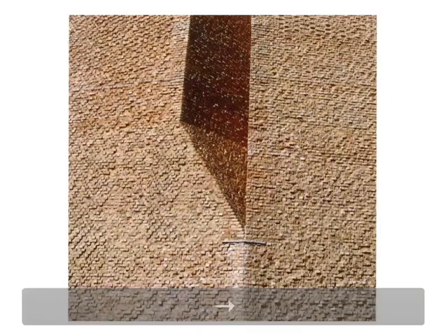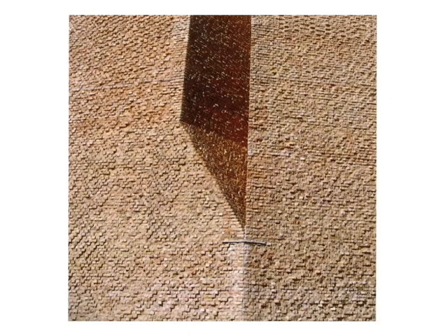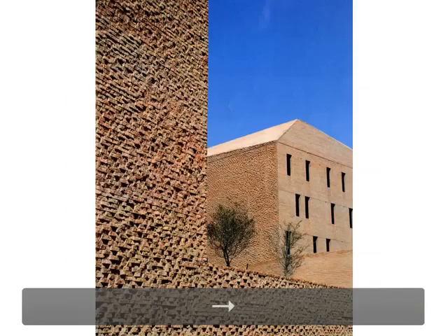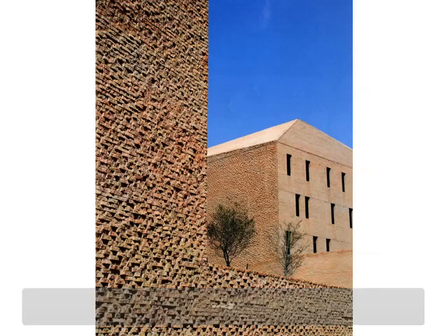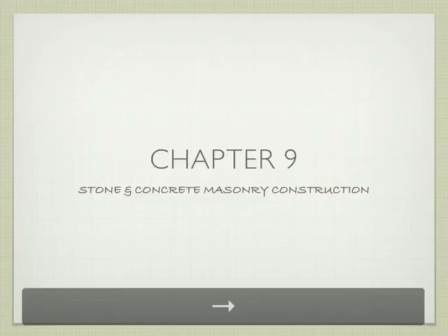So we can end up with something like this on the outside of the building, right? This would be a relatively challenging shape to try to make if it was a structural wall, right? But we have steel behind in this case that's providing the primary structure, and we can create these kinds of definitions on the surface veneer, right? Because it's only that little thin veneer, right? And so if we're looking over here, you can kind of see those little depressions that go up to the windows on the undersides of the windows. And obviously this was a lot about the exposure of that brick and that rough textured surface.